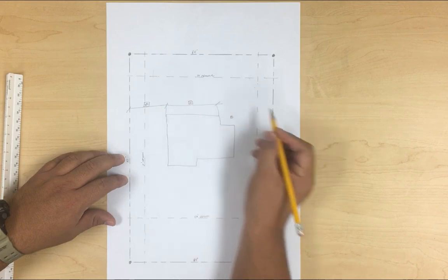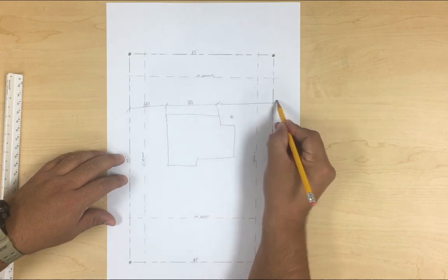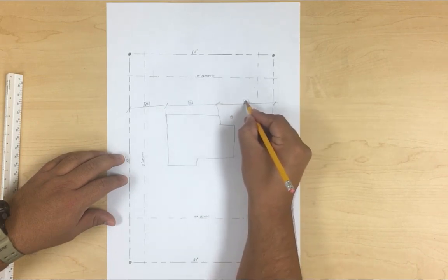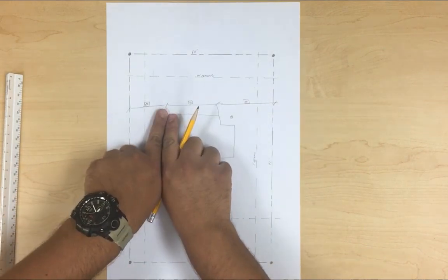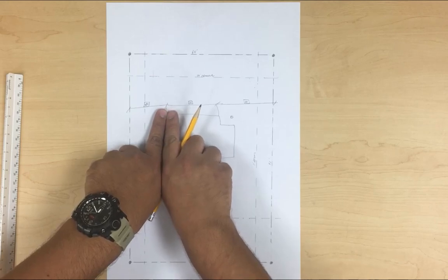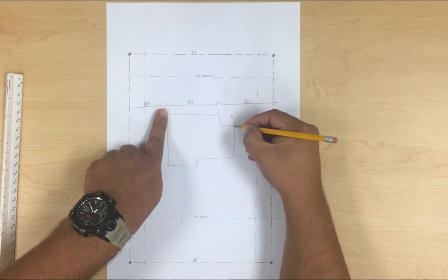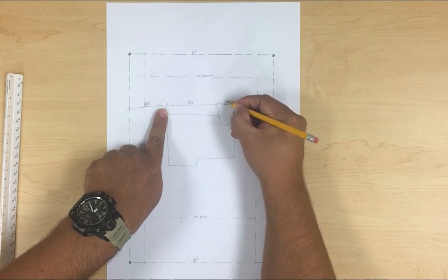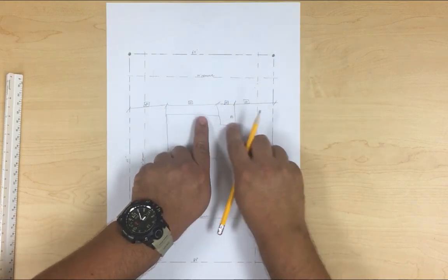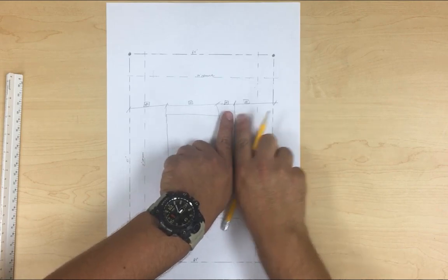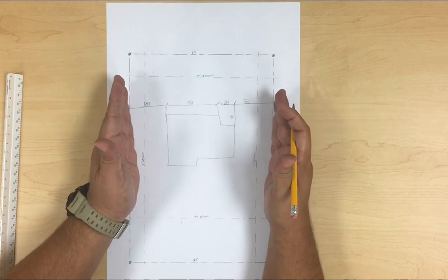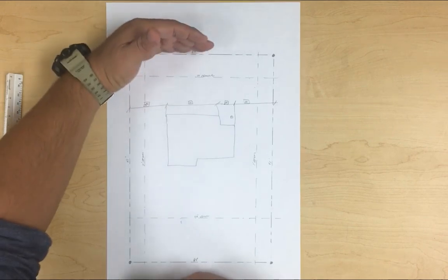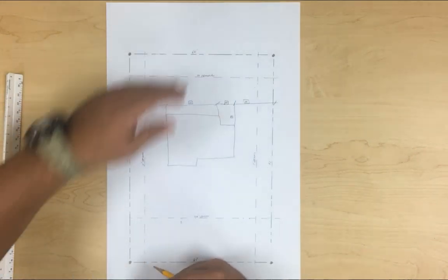So you can have a dimension there with a number, and then tie it back to the property. We're telling them from the property, go so much this way, that's where the house, or the edge of the house, is going to start, and then it's so much to this point, actually we missed this one. And then it's so much this, so they can plan for that, and then from here tie it back to the dimension. So now we know where the house is in relation to the front dimension. Now, where exactly is it in relation to the 95 feet? So we'll do the same thing.